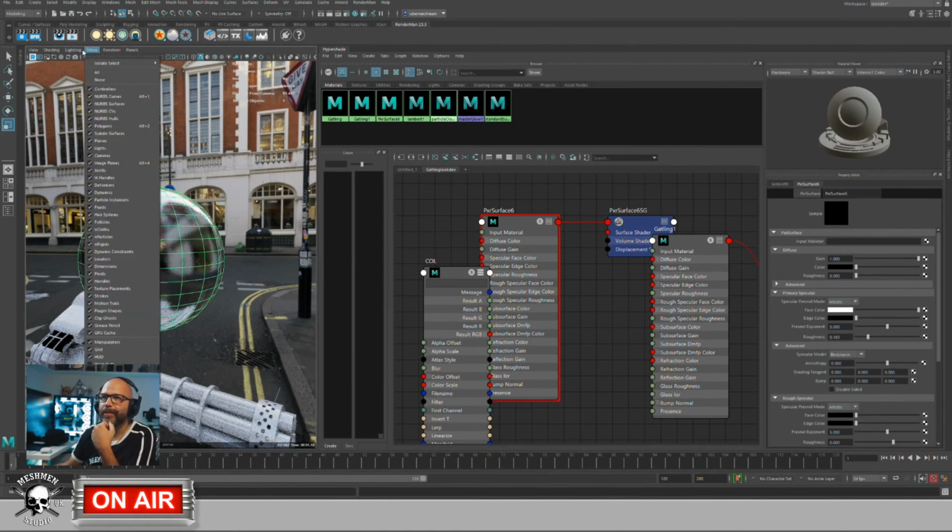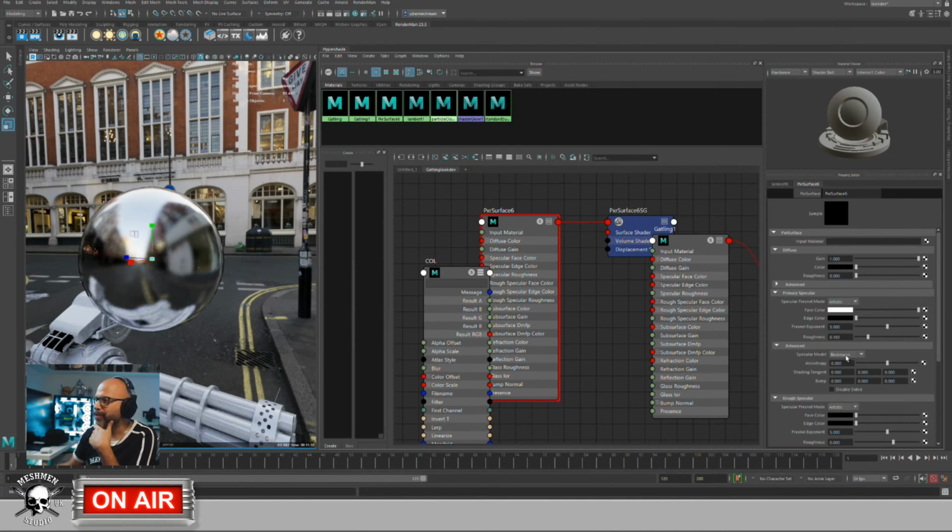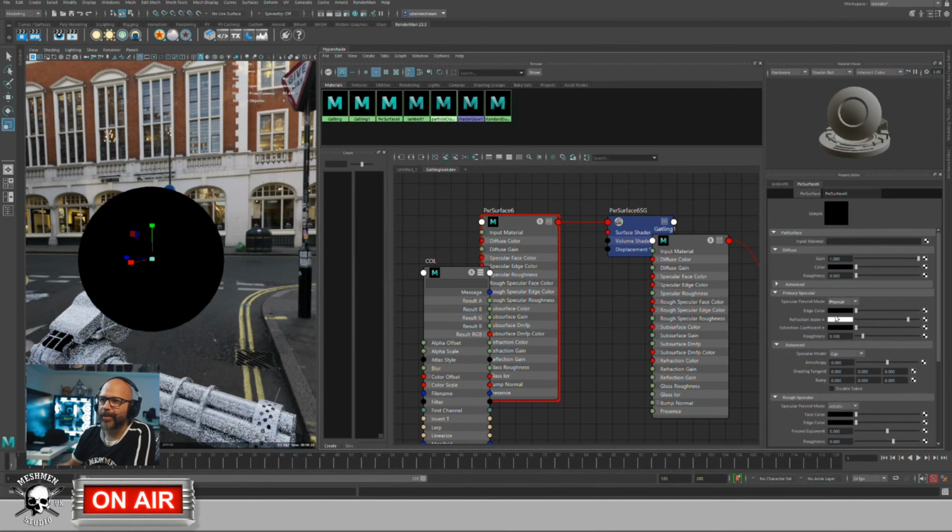Let's actually turn off the selection highlighting so we can see it. You can see here now it starts to blur out because I have increased the roughness. But when I now go from Beckmann to GGX, we're going to see a bit of a pop. It's not as visible here in the IPR, but with some values, when we have a bit of roughness, I think the GGX behaves better with roughness. We can see it here on the sides of the reflection. It starts to have a bit of a tail in the roughness, rather than physical.